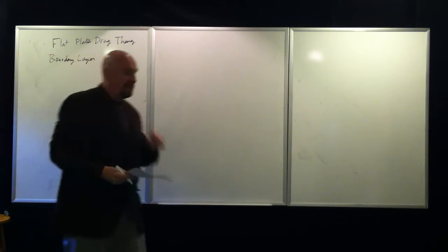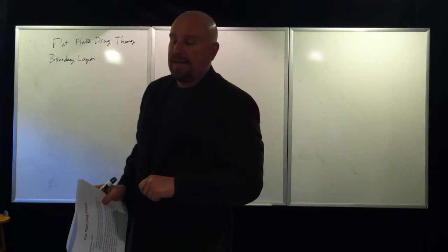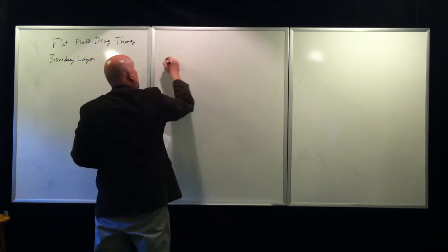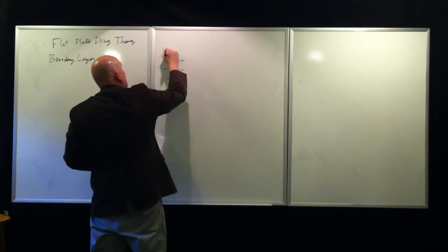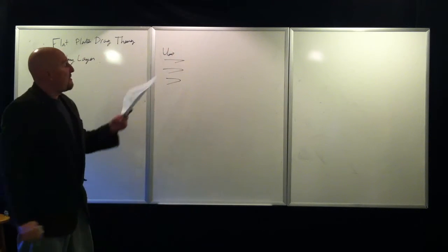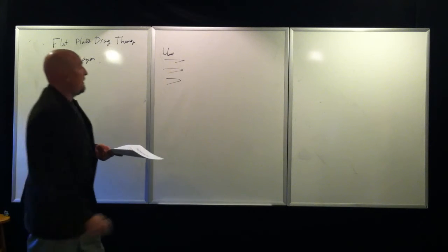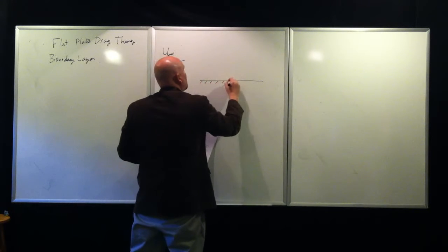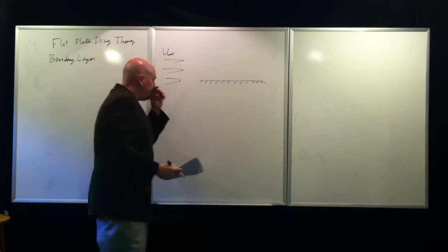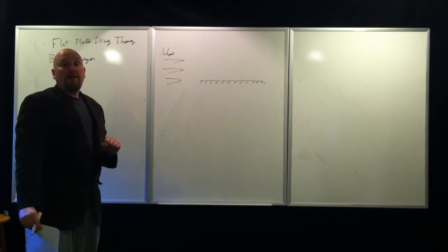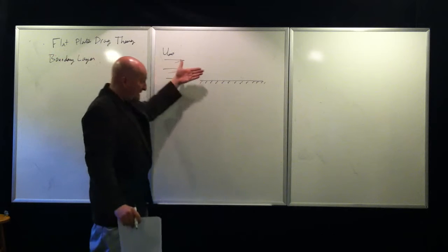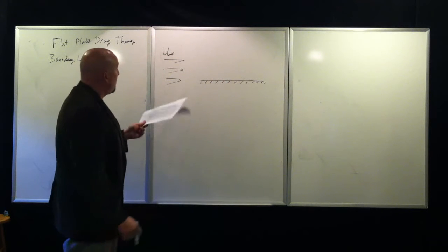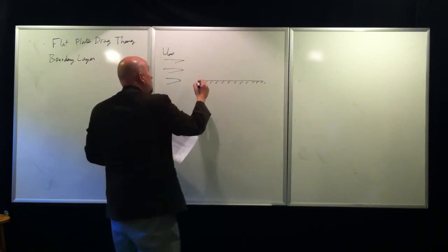what I want to discuss, and we've alluded to at a few different times in the lectures, is a boundary layer. So, if we have a free stream velocity coming in, it's going to have the fluid going over a flat plate. This is going to represent our flat plate that's in the free stream. The fluid will have a density and a viscosity. The viscosity, as we went over, you can think of that as sticking to a particular surface. A boundary layer is going to develop.